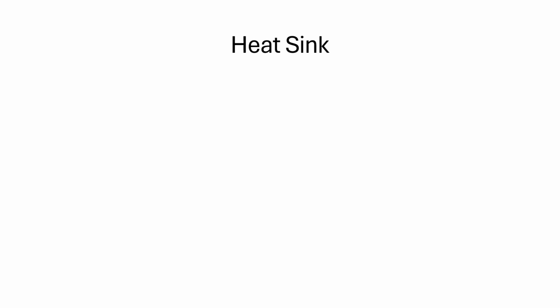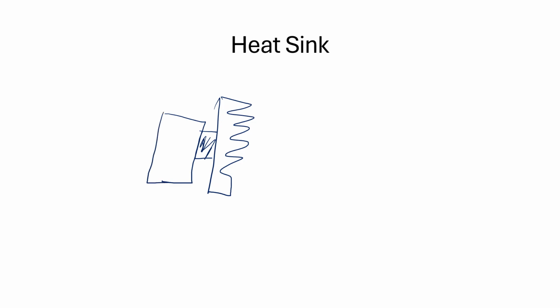In order to avoid this, heat sinks are provided along with the semiconductor devices. A heat sink is a mechanical device. It is connected to a power transistor in order to dissipate the heat generated. For example, I'll just draw a simple diagram of a heat sink. Let it be like this with a mounting surface. Where is it mounted? It is mounted to a junction in a case.